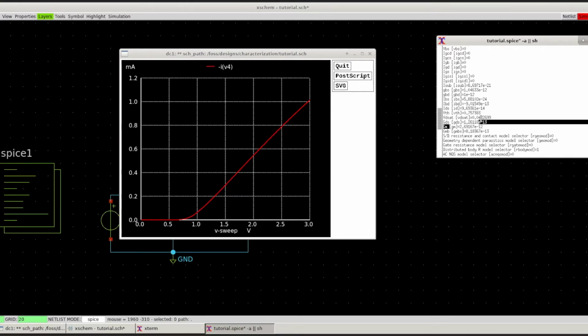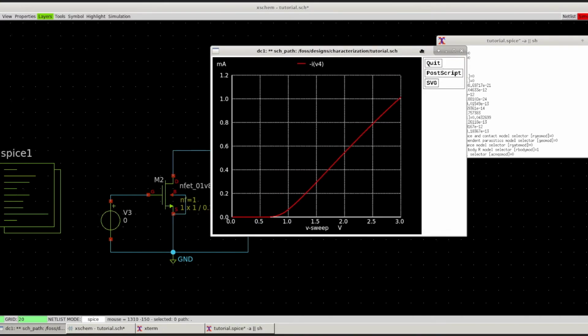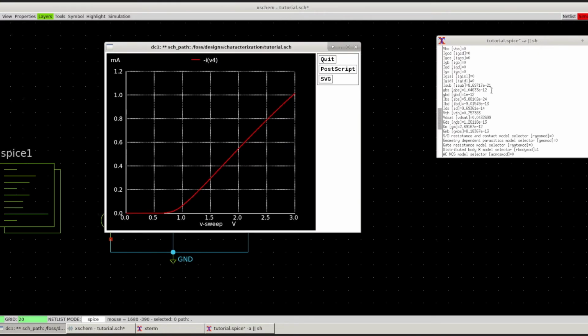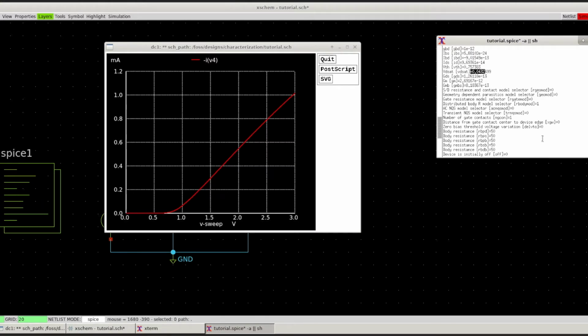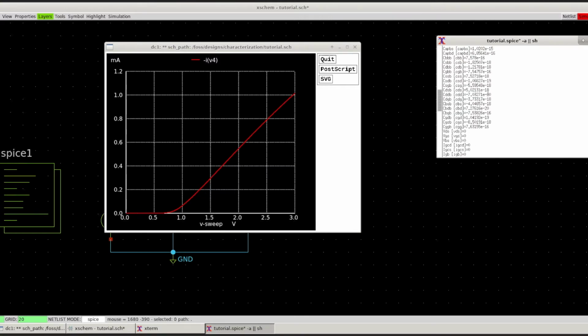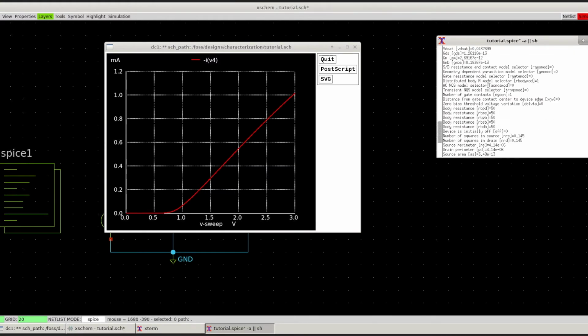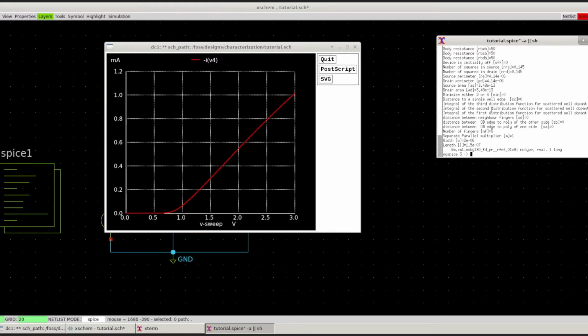You can see here we have a very small gm because it's a very small MOSFET with a width of 1 and a length of 0.15 micrometer. It has an estimated threshold voltage of around 0.757 volts, an estimated saturation point of 0.433 volts, and some other calculations that help with capacitance, resistance, and the physical size of the transistor, based off of the parameters and the PDK's idea of how you would lay out that FET. Okay, cool.